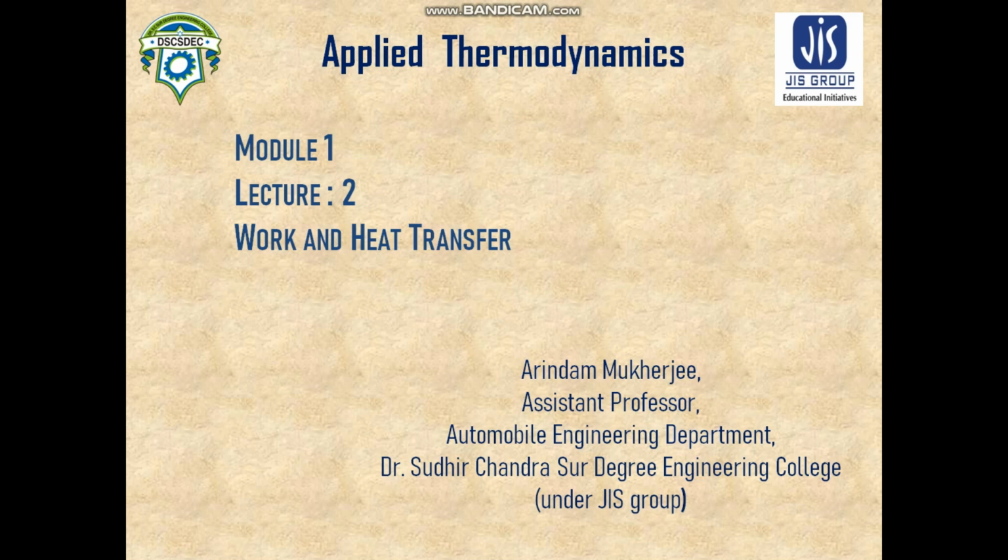So let us start where we left off. We are discussing quasi-static process and thermodynamic equilibrium. We have understood that these two are the basic requirements for a thermodynamic process. For any kind of thermodynamic process, we always assume that the process should be in thermodynamic equilibrium and all the intermediate states should maintain a quasi-equilibrium criterion. So this has to be followed. So let us start with that.